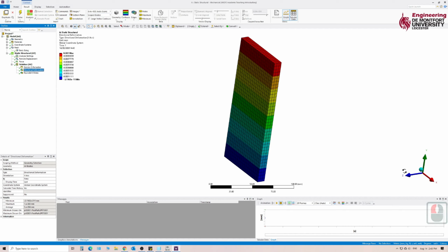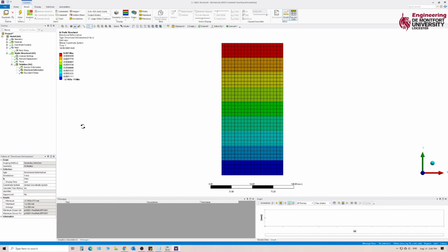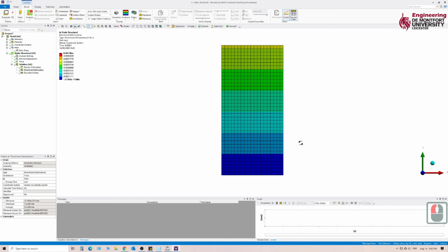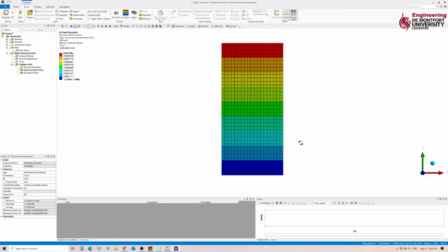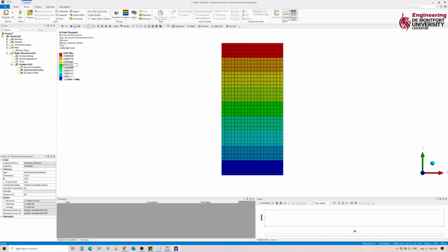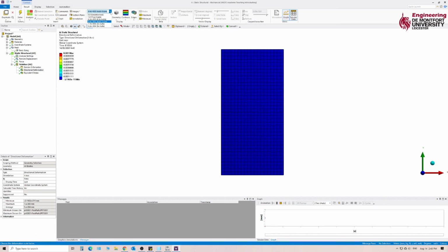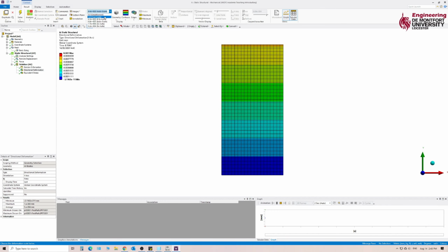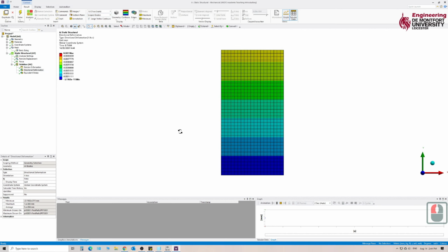So if we click on these, let's change our view up. So this shows us the deflection. And if we have a look at the units, so okay, the maximum deflection here is 0.01 millimeters. We can animate this, so we can see, okay, it looks about right to me. If you're applying force in that direction, you'd expect it to move in that way. Something to remember though, that this is an exaggeration. You know, we can change how much it moves. You can change it to undeformed, true scale. If we do true scale and animate it, you'll see that you can't actually see it moving.